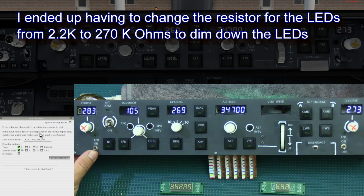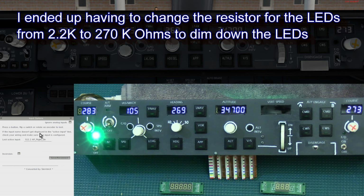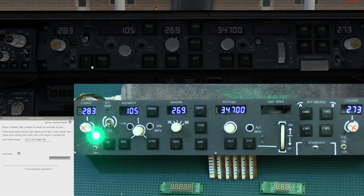Let's do the flight director here. You can see that the flight director in the simulator turned on and the light came on, just like it did over here. But you'll notice right off the bat that it is extremely bright. I used a pretty high resistor, I think a 2.2 kilo ohms, to try to bring down the brightness of the LEDs, because I knew that they were bright ones. But nevertheless, it's still like that. The only thing I didn't notice, oh yeah, there it is. I was expecting to see something down here, but it was up here, the function of that switch.